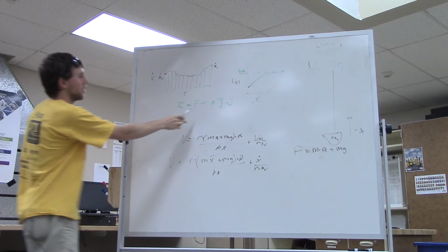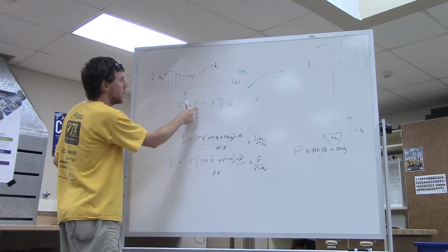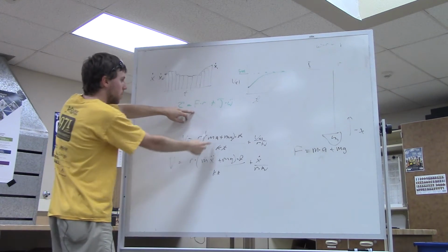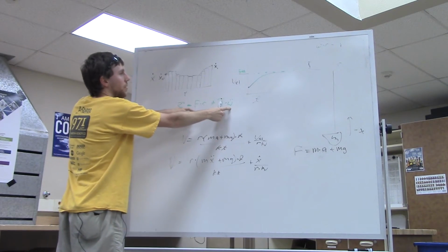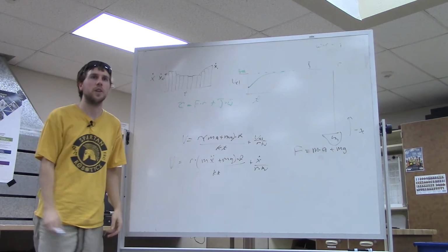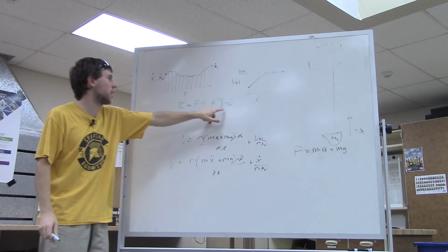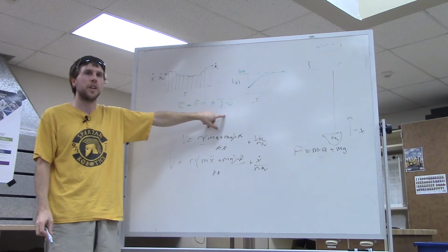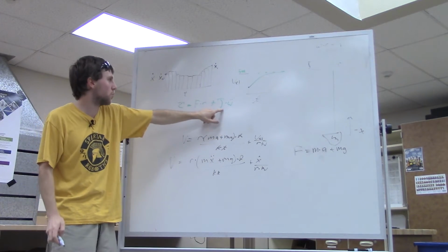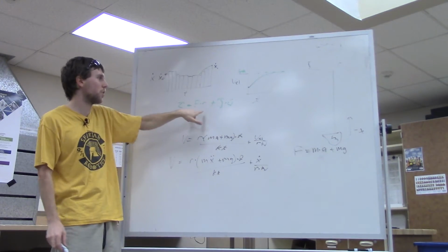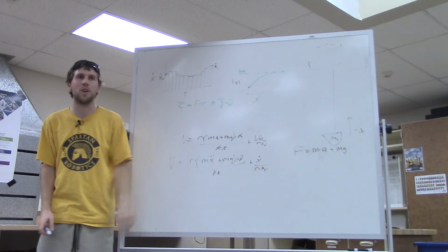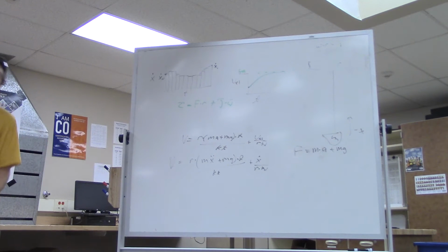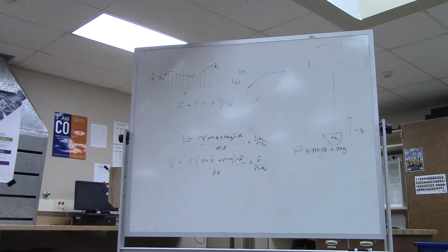Now, as we plugged things in for F, we got x double dot, and we have an equation relating omega double dot to x double dot. So this is just another scalar, another part of your mass term. And if this is way, way smaller than the resulting part over here with your mass, then you can ignore it. So for a big, heavy elevator and a little 775 Pro, it's not worth measuring the inertia of your gears and the inertia of your windings. You can just ignore them.